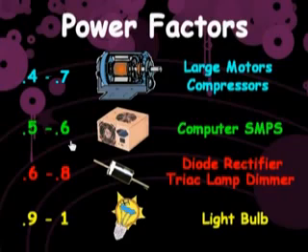produce no watts. A power factor of 0.8 means that 80% of the amps flowing in the electrical wires produce watts for this lamp dimmer and light bulb, while 20% of the amps are harmonic currents that produce no watts. A power factor of 1 means that 100% of the amps flowing in the electrical wires produce watts that power this light bulb.